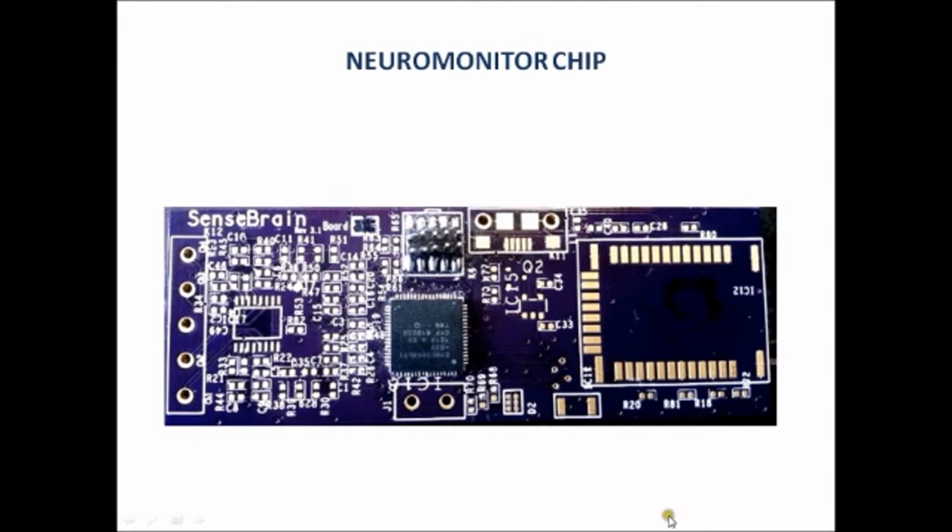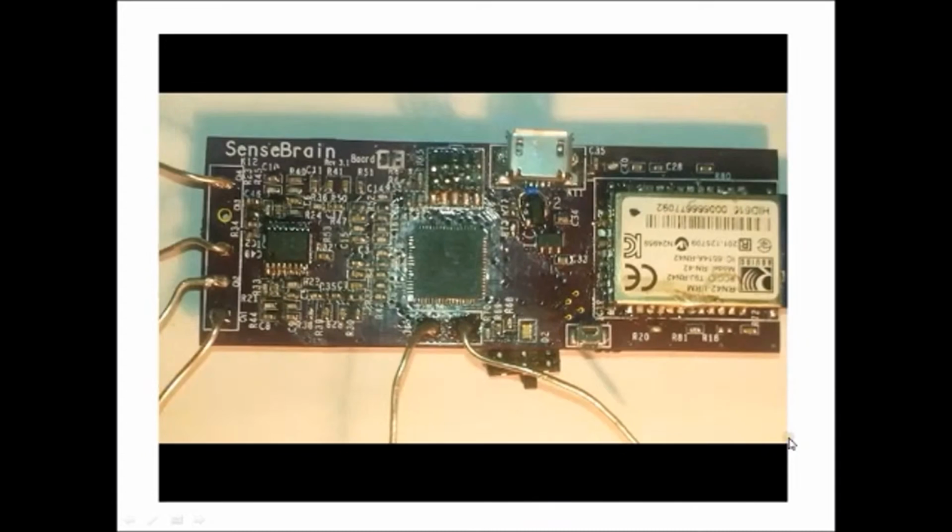This is how the board looks like. The golden things here are the pads where the components are populated. The technique to populate these is that you put a small amount of solder paste here, then you transfer your component and then you use a hot air current to solder it. I'm going to show a video of how a soldered board looks like.